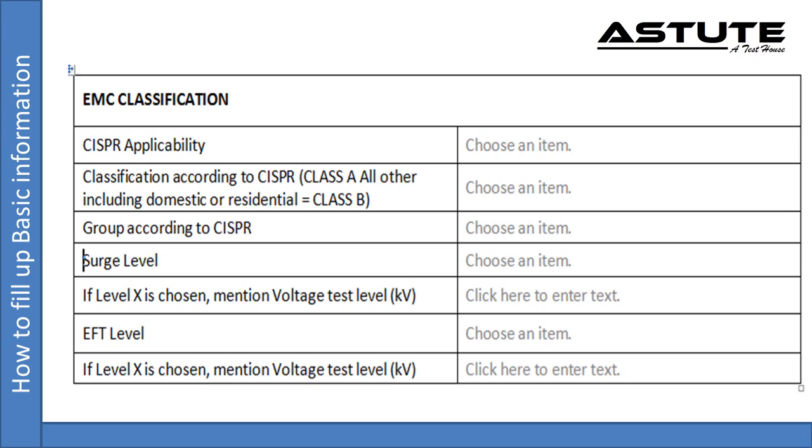The electronic equipment has its power supply completely separated from the other equipment. Switching operations can generate interference voltages within the room. Surge voltage may not exceed 500 V.